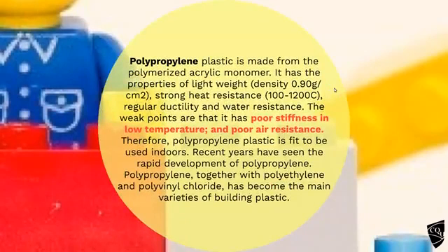Polypropylene. This one's quite better. This is really good. It doesn't go soft. It doesn't catch fire terribly easily. It does have weak points again. It's not stiff if it gets cold, so it can shatter, snap and split in very cold temperatures. And it's not very good at keeping the air out. You wouldn't use it to create an airtight room or something like that.